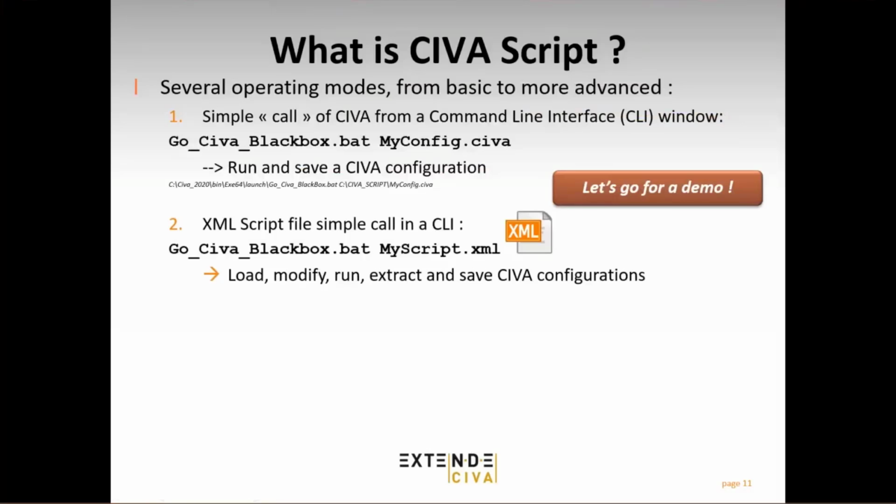And second, this XML script file could also allow you to extract data, because the extraction of results may sometimes be a really time-consuming part of the manipulation of a simulation tool. So thanks to an XML script file, you can not only launch and run, but also modify, driving a series of simulations and extract results. Let's see an example of an XML script file.